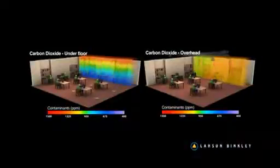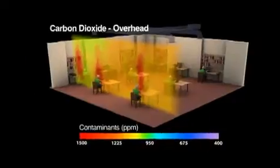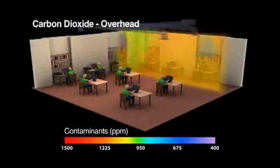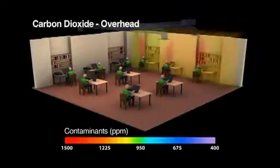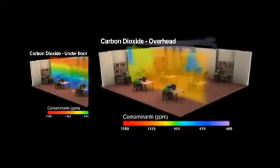Here we have a similar graphic showing carbon dioxide profiles. As with heat, contaminants in the ducted overhead system are thoroughly mixed, keeping contaminants within the space for long periods of time. This makes the quality of the space and the return air virtually the same.